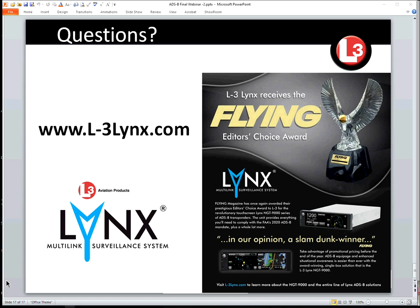However, with that being said, when we built the Lynx device, we mimicked the protocol that we used with Skywatch. So all of those legacy displays, your Garmin 430s, 530s, even the newer ones, the 650s, 750s, G1000s, all of those, the Avidyne displays, the 540, 440, the EX500, the Pro line, the Honeywell, all of those that had the Skywatch interface, which is just about everything that could display traffic, could display the Lynx traffic.